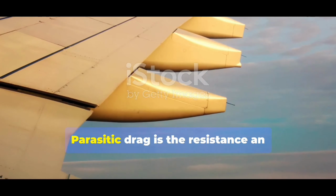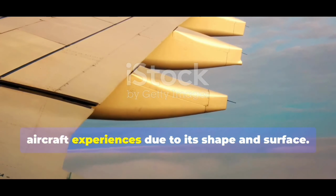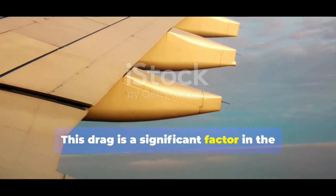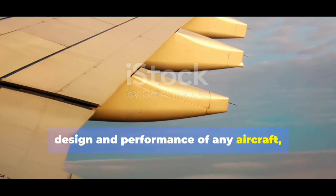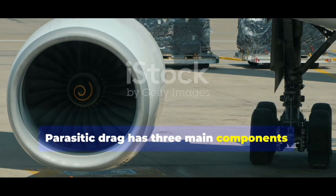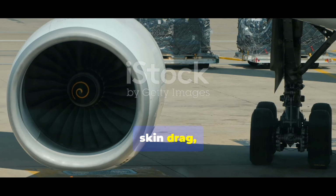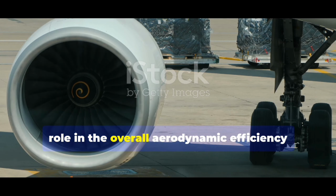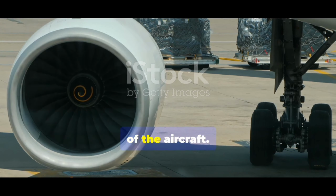Parasitic drag is the resistance an aircraft experiences due to its shape and surface. This drag is a significant factor in the design and performance of any aircraft, affecting its speed and fuel efficiency. Parasitic drag has three main components: form drag, skin drag, and interference drag. Each of the components plays a crucial role in overall aerodynamic efficiency.